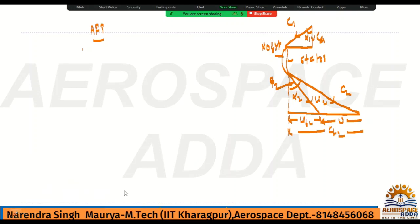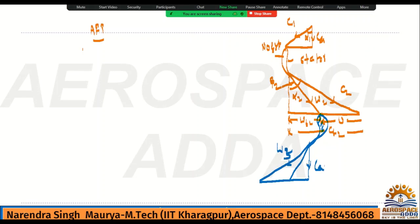Now we have rotor here, so this is the rotor. So rotor will get velocity, and that velocity will be rotor velocity here, relative velocity, and from the rotor again the relative velocity will go from outside, like this. So this will be omega 3 relative velocity, and this will be, obviously, axial velocity which is constant throughout, and this will be absolute velocity C3.